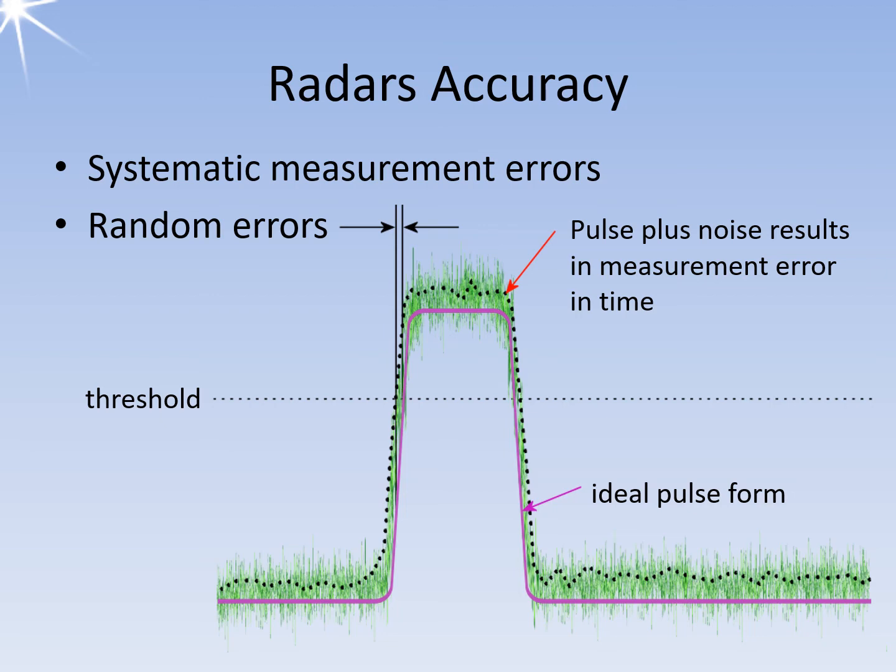With a pulse radar, the runtime is generally measured from the rising edge of the transmit pulse to the rising edge of the echo signal. The accuracy of this measurement depends on the magnitude of the clock frequency for this time measurement. Measurement results between the cycles aren't possible and generate a systematic measurement error. The accuracy depends also on the size of the individual range cells in signal processing.